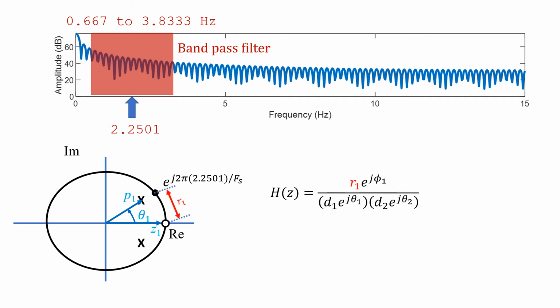So that is r1. Now, the interesting thing here is that as I approach the 0 frequency, that distance r1 becomes smaller, to the point that where I'm almost at the top, that distance will eventually become 0, completely blocking the 0 frequency here, which is something that I want.